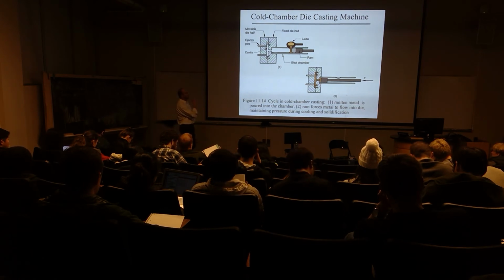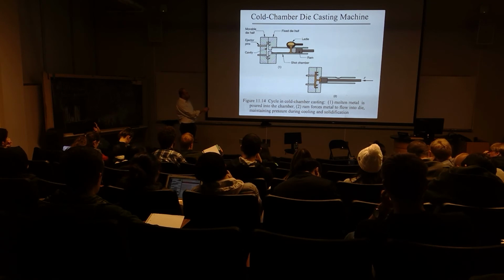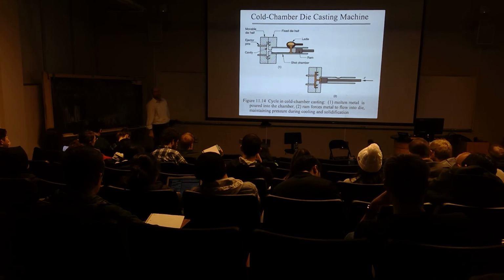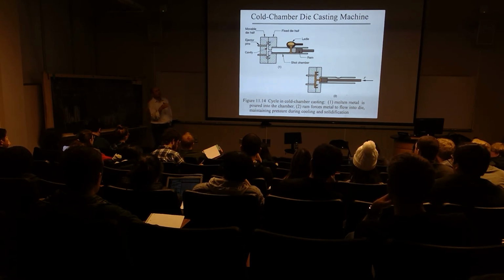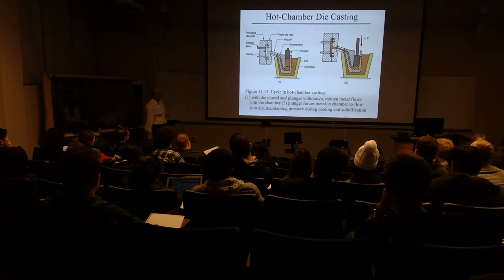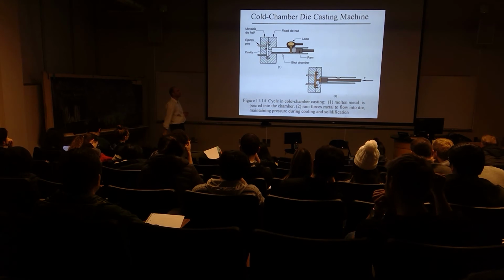So in a cold chamber die casting process, that means that the metal is brought to the mold from an area remote from the furnace. And that means that the metal is much cooler at introduction to the mold and is done as a single controlled volume shot process. It's done under much higher pressure because the metal has much higher viscosity. It is much less like a liquid. It has a resistance to the flow of its introduction into that particular mold. But that also is, again, important in just comparing the cold chamber to the hot chamber. This material will likely have more time for changes in grain growth. We're going to talk about it next.